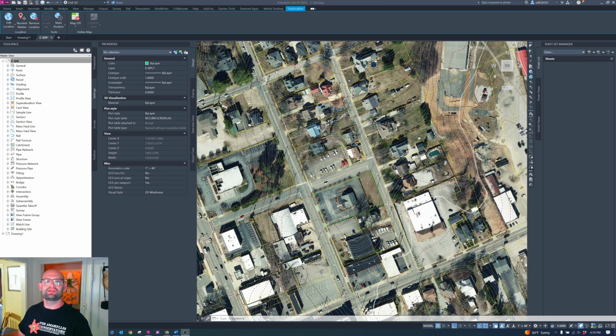On to the important commands from the day. For importing shapefiles, we use the command MAPIMPORT. Go ahead and select a relevant area first, and don't forget to create that object data before you hit OK. MAPINSERT, that's the command we use to import the SID image.